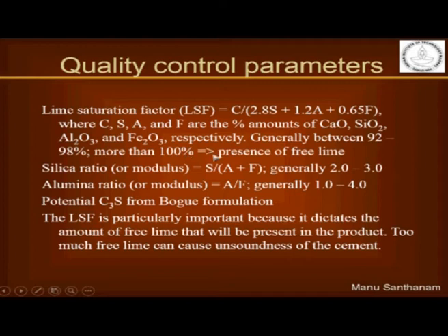If you have more than 100%, this indicates the presence of free lime in the system, which is going to be a disadvantage for the cement. It is going to cause unsoundness in the cement.